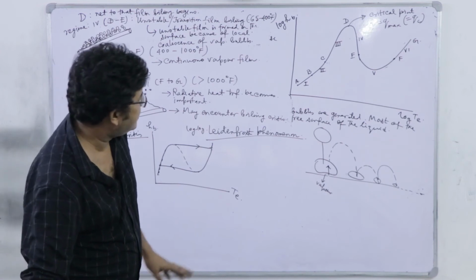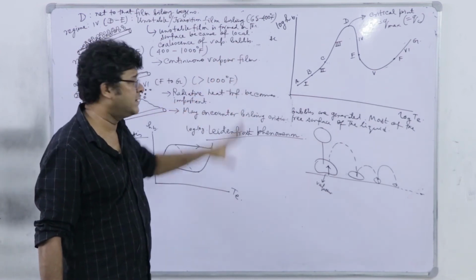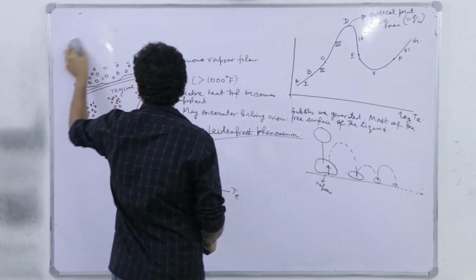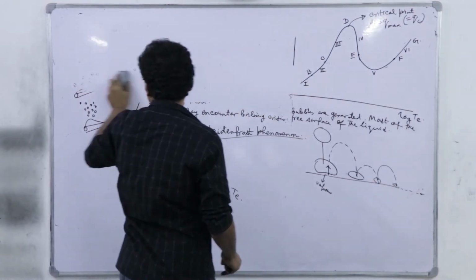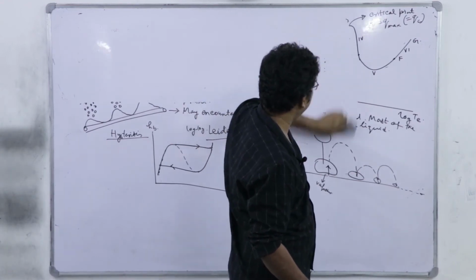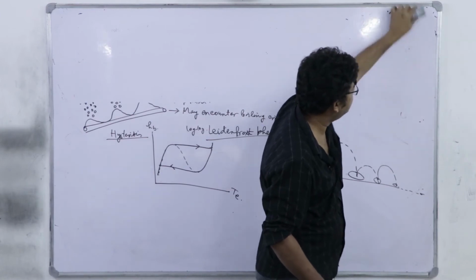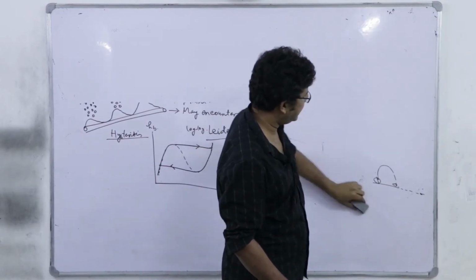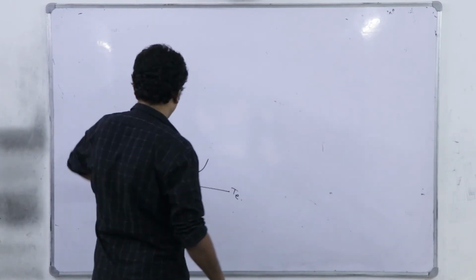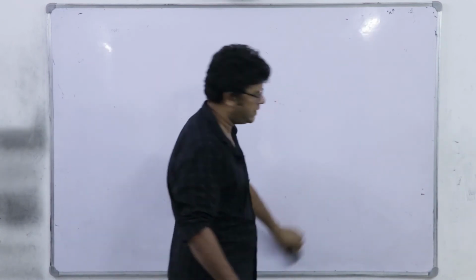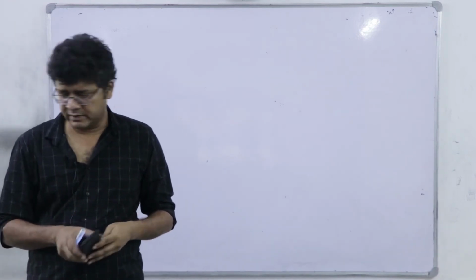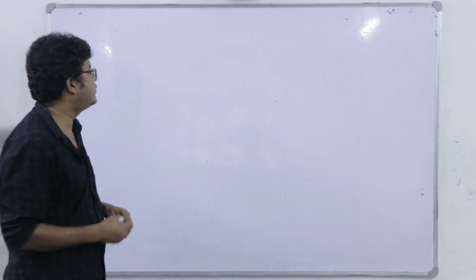Now, that's all basically, qualitatively we have discussed about boiling. Now, regarding the mechanism of nucleation, you see what happens generally, there are two different types of boiling or respective bubble nucleation. One is homogeneous, another is heterogeneous. So homogeneous boiling, as I mentioned, is rarely encountered in industrial situations. Mostly we have the heating surface, and there we have this typical heterogeneous boiling.